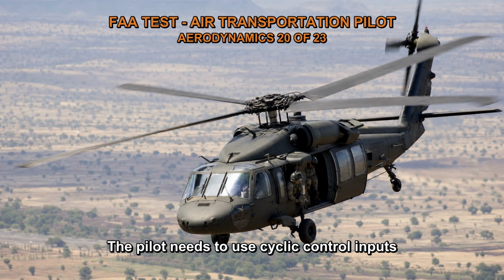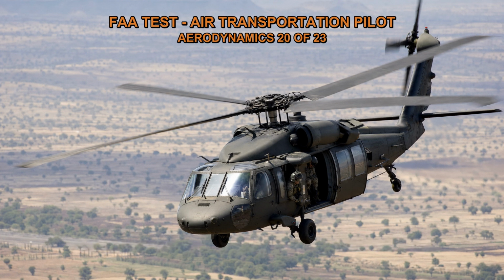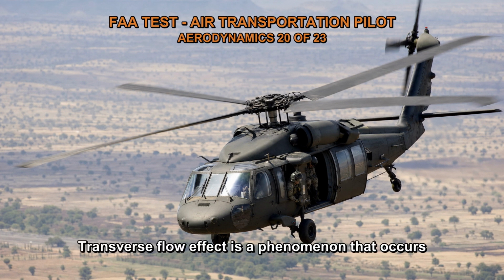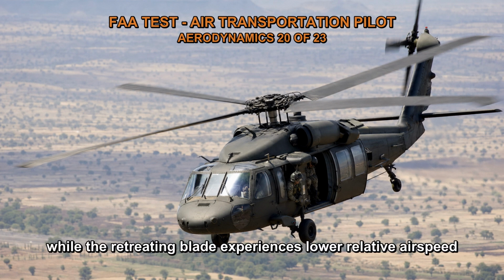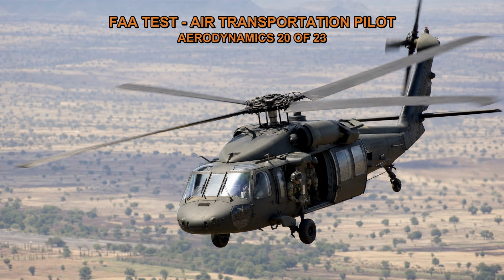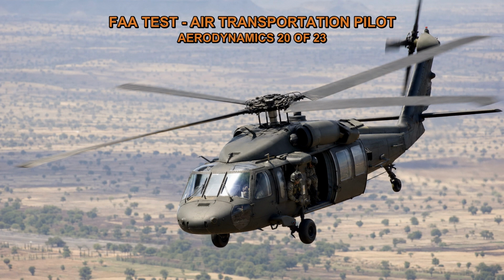The pilot needs to use cyclic control inputs to counteract this translating tendency and maintain a stable hover. Transverse flow effect is a phenomenon that occurs during low-speed flight or hover where the rotor's advancing blade experiences higher relative airspeed and lift, while the retreating blade experiences lower relative airspeed and lift. This leads to a lateral flow of air across the rotor disc and can cause asymmetric lift distribution.